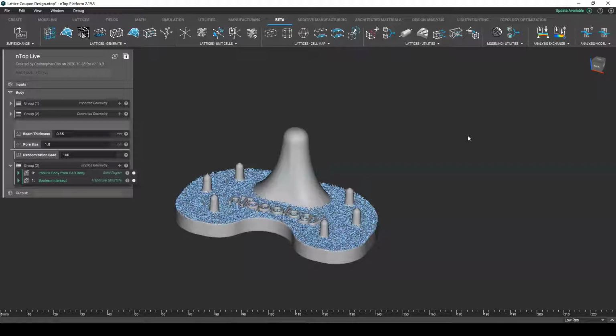The alternative, as a result to sacrificing one of those parts, is to fit smaller and functionally representative test coupons somewhere in your additive manufacturing build where they don't take up a lot of space or use a lot of material. Now, there are many other reasons why you would want these coupons and strategies for where you would place them in your build,